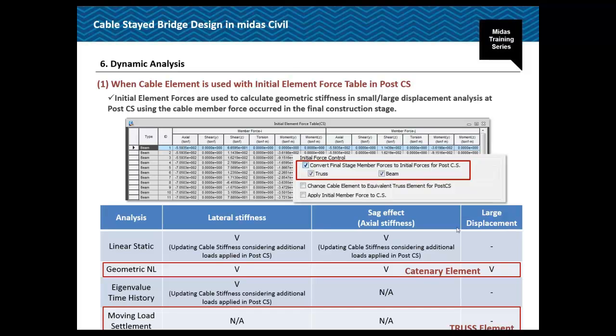But what about the linear static? In the case of linear static, surely large displacement will not be considered, but since we used the cable element, the program was able to consider the lateral stiffness and the sag effect. So that is good, and it has no problem.